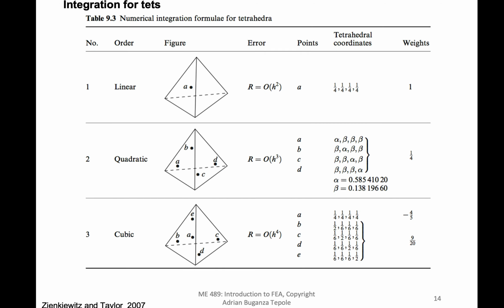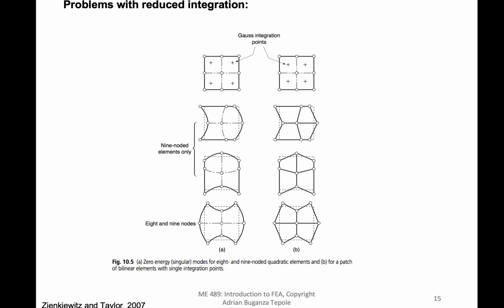There are integration schemes for tetrahedra. There are integration schemes for hexahedra elements. But going back to this question of reduced integration versus full integration, and to what we saw in the Abaqus lab that we did, with reduced integration elements, you might have these unstable modes.